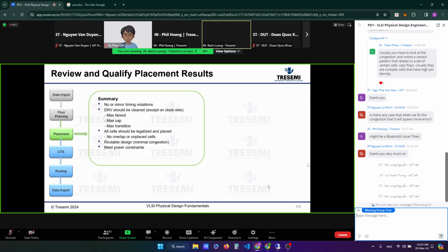Yeah. In a given technology, that is the range they characterize, so the data within that range are accurate. If it's far outside that range, they extrapolate. So within that range, that square that Phil was showing, is pre-characterized for that particular technology. So when you do timing signoff and you have extrapolation, that means you're asking for trouble. Your silicon might not work. Right? So I think it's critically important.